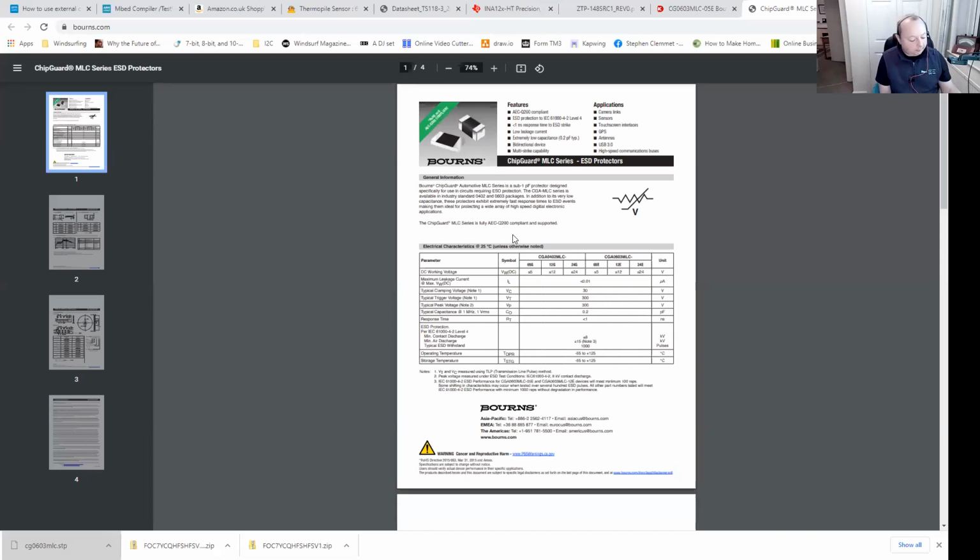Yes. So when we're talking about logic inputs, and if you're running over cable, I put these tiny surge arrestors. You can get these from all good electronic suppliers. I'll usually put one between the input pin and the ground, so if you do get any transients over cables, you'll protect the circuit.